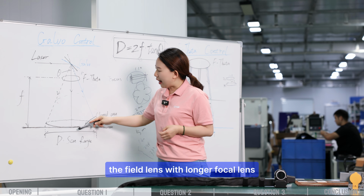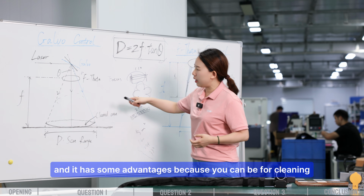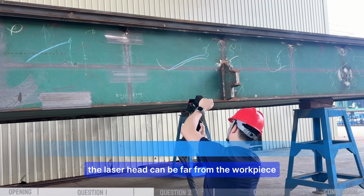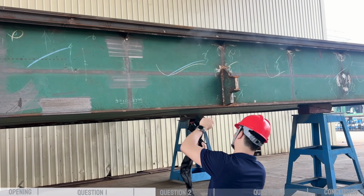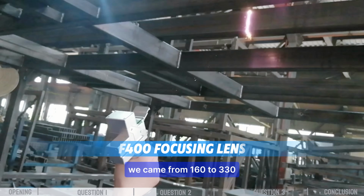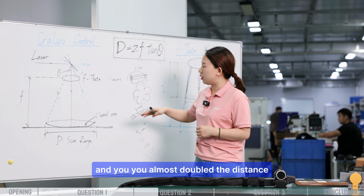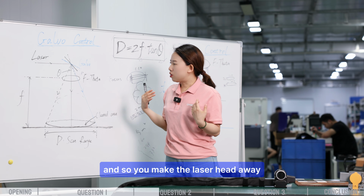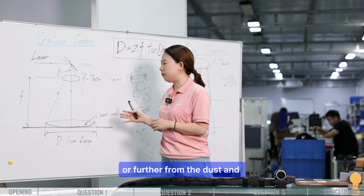A longer focal length has some advantages, because for cleaning, the laser head can be far from the workpiece. The focal length goes from 160 to 330, almost doubling the distance, so you make the laser head farther from the dust.